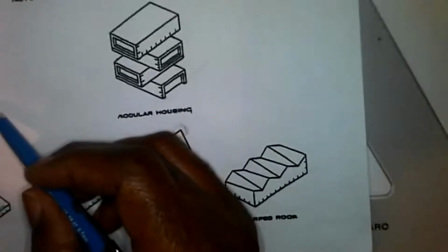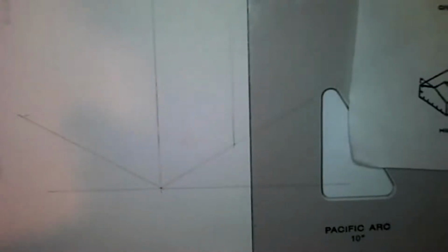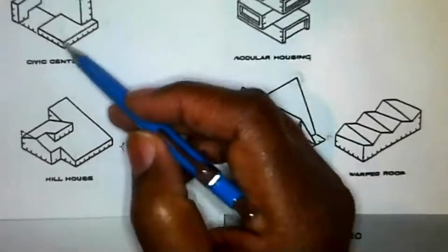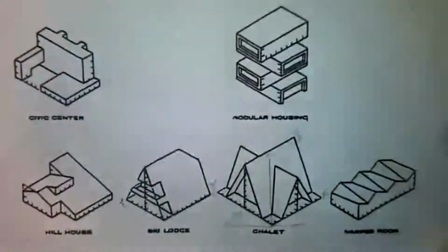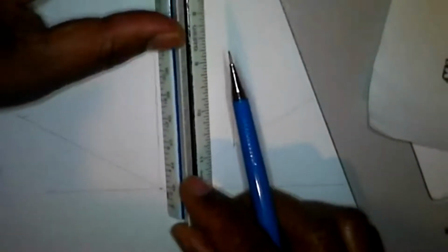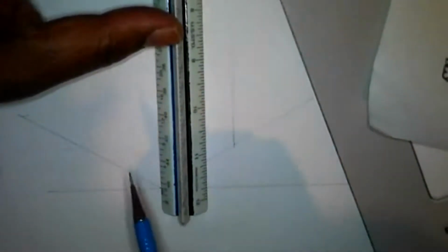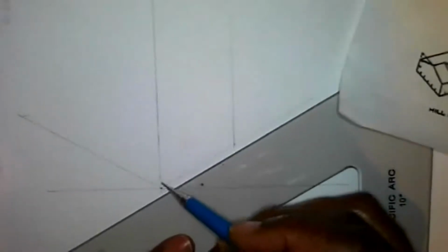So now what I want to do is establish the height of this wall right here, and that's 1 unit. So I'm assuming that's going to be 2 feet. So I'm going to come over here at 1/8 of this scale. Okay, I'm going to go 2 feet. Now I'm drawing that line along the x-axis, so it has to be parallel to it. So see, I measured up 2 feet, established a reference point. Okay.